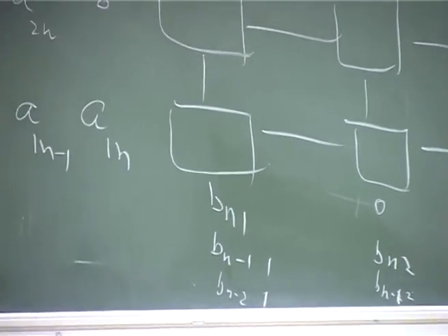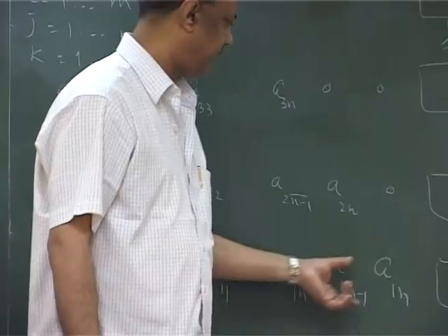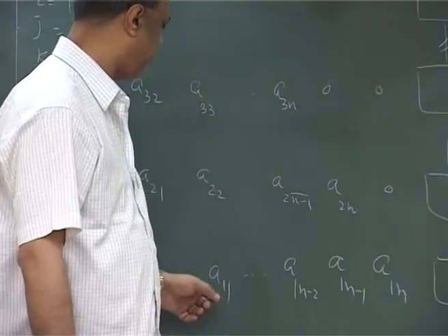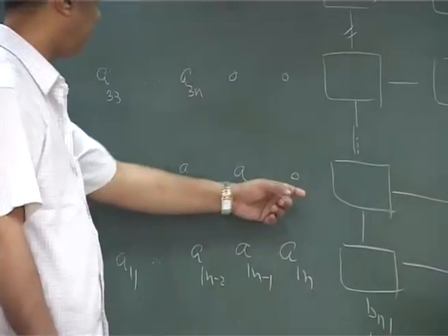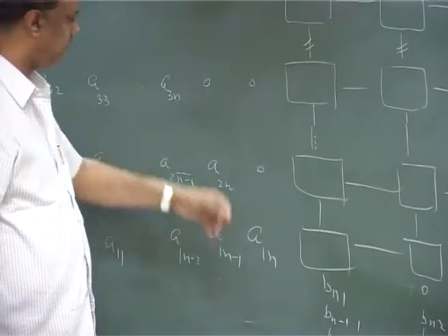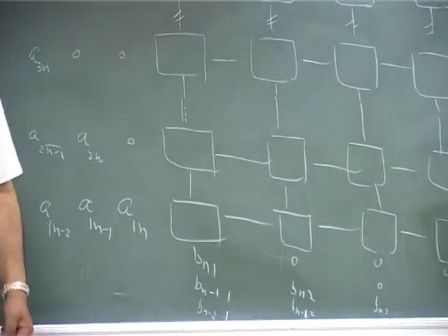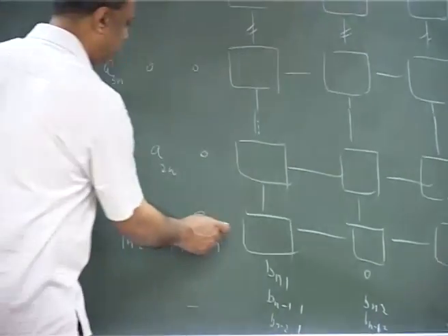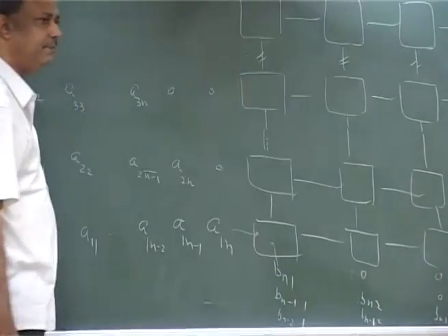See, the data is arranged in this form, right? A11, A12, up to A1n are nearer to this, and then one delay is here, for A2 a delay, and so on. Similarly is the case with matrix B. Now, you move this data after one cycle and you observe that they are multipliable.